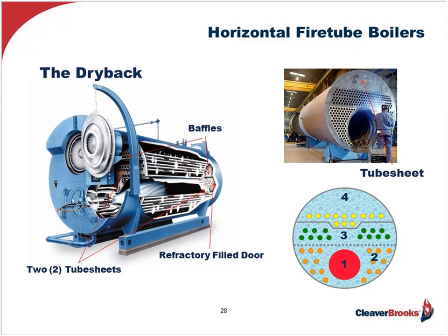Now, from here, all you have is hot gases traversing through the respective tubes, convectively and conductively transferring their heat before exiting. Then baffles, as indicated with the red arrows in that left-hand diagram of the cutaway, consist of both refractory and steel baffles that form the divisions for channeling the flow between the various passes.